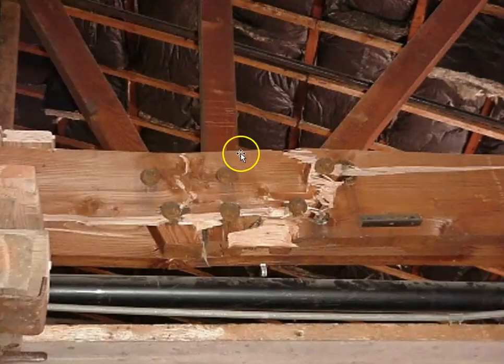Here, a homemade, site-built truss. Large connectors in principle could be a good thing, but when you take out that much material from the beam, it becomes a weak point. So not surprisingly, it appears like some sort of tension has pulled all of this apart. And not surprisingly, all of the damage occurred at these connections where they removed a significant amount of material from the beam.